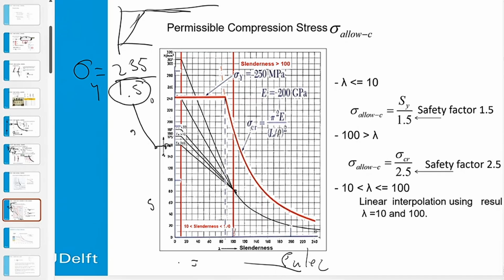While at the Euler buckling limit, the Euler buckling limit has a different characteristic, because if you have Euler buckling failure, then that's it. There is no increase in stiffness which saves you. When it collapses, you do not get an increase in stiffness.